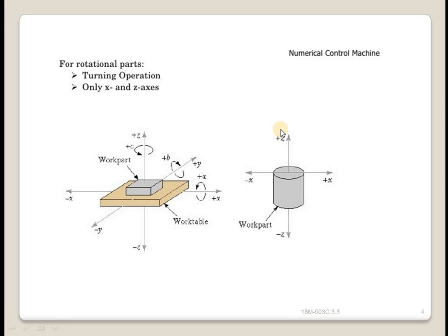The location of the 0 point is communicated to the machine operator. At the beginning of the job, the operator moves the tool under manual control to some target point on the table. So the target point is some convenient place on the workpiece or the table for the operator to position the tool. For example, it might be a pre-drilled hole in the workpiece. The target point has been referenced to the 0 point by the part programmer.